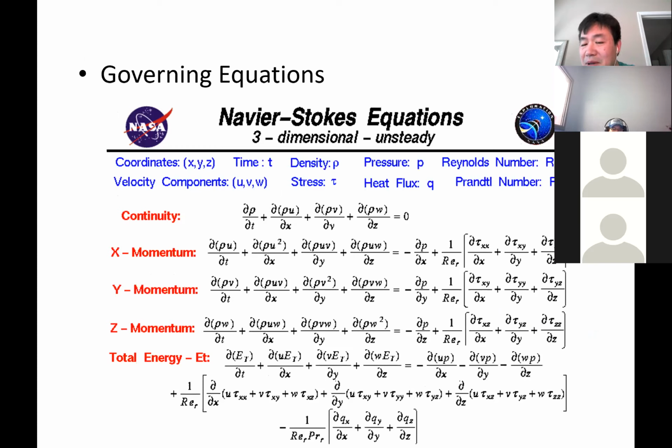So what we do is simplify this into linear algebraic equations. These equations are not linear. Look at the terms in the momentum equation: the second, third, and fourth terms are the three nonlinear terms. That tells you the shape between two points is not a straight line. We can solve algebraic equations using matrices, so we have to break it down and transform it into linear equations, assuming, for example, a straight line between the two points.